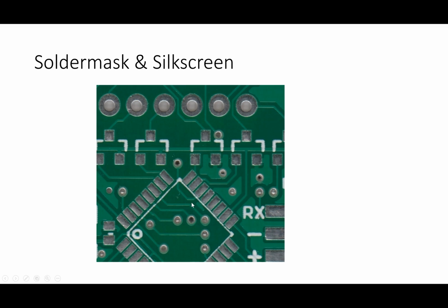If I look carefully at this board, I can see these lighter green areas, and then these darker green areas. Where I have these lighter areas, that's basically where there's copper sitting on top of that FR4 substrate. So here I can see I've got a big copper area. This is what is sometimes called a copper pour, where copper is effectively in a large plane. So we'll use that terminology, a copper pour. These other skinnier areas right here are copper traces.